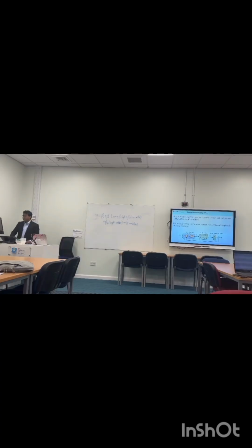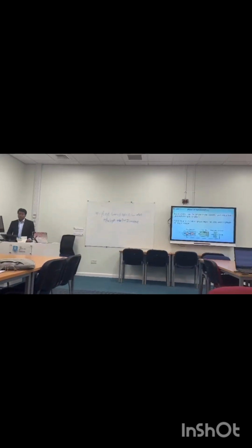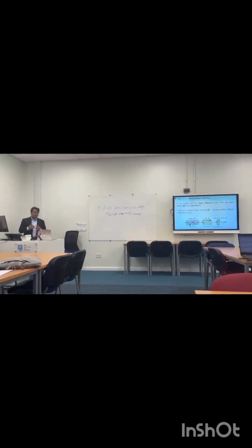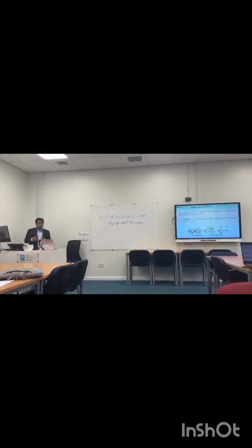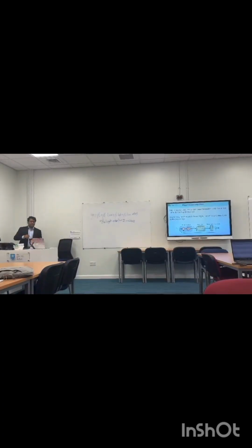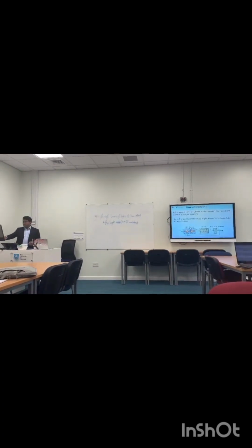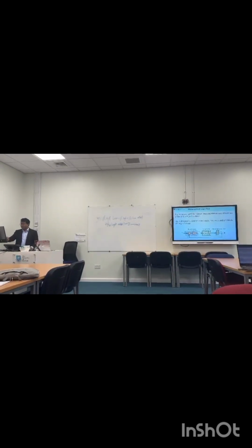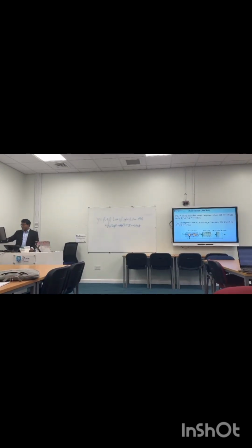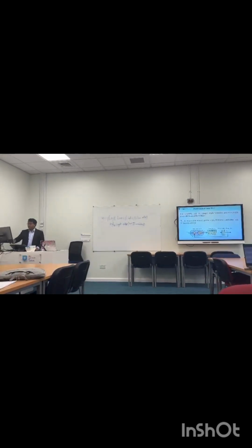The PLL is designed to extract the phase angle, frequency, and amplitude of the grid voltage. Because of distortion, noise, or some other reason, if the angle is distorted, then it can be corrected due to the closed loop. You can see the block diagram, the phase detector, loop filter, and the phase angle, and I will show you more later. It is always a feedback.